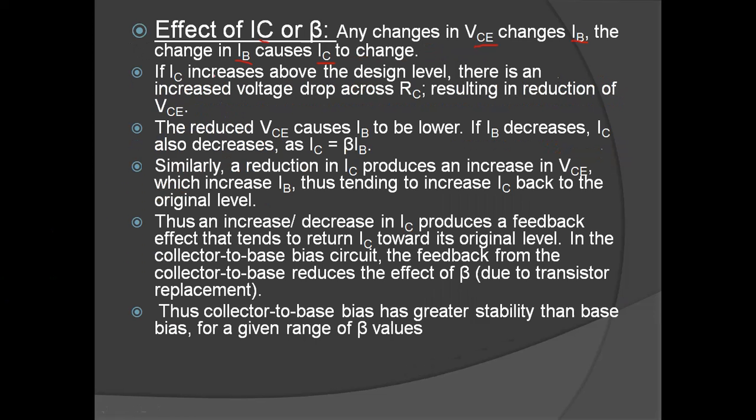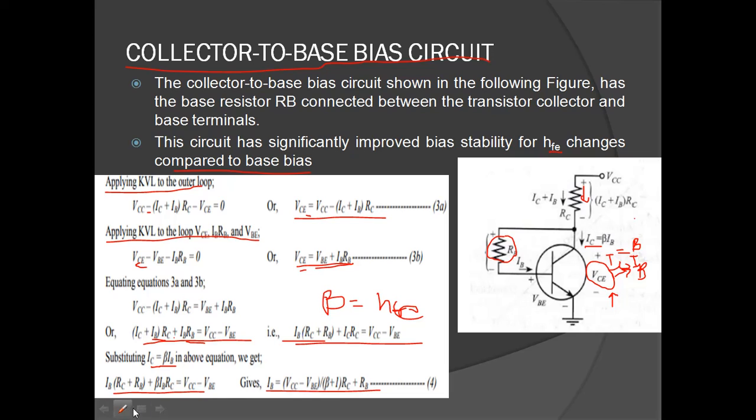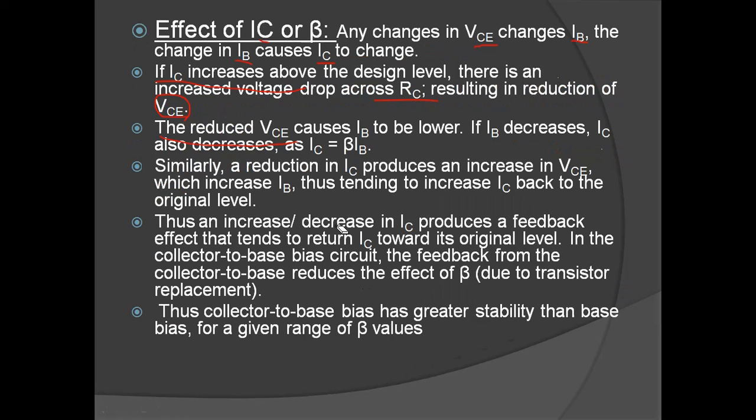If IC increases above the design level, there is an increased voltage drop across RC, resulting in the reduction of VCE.